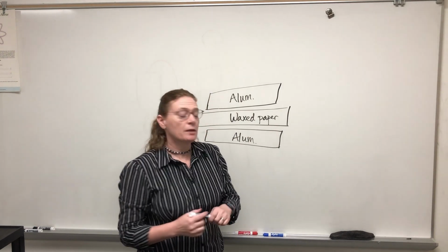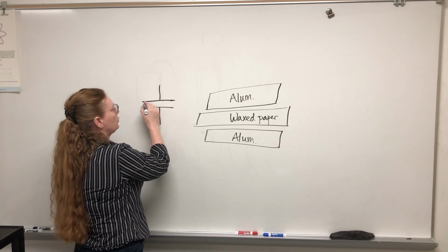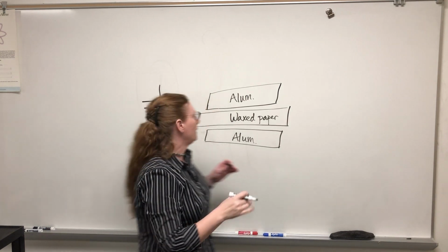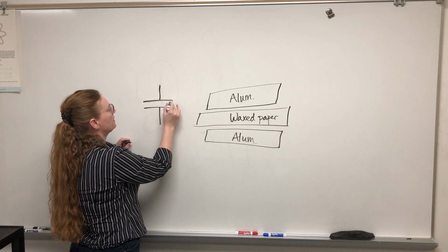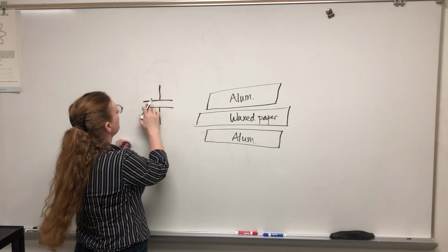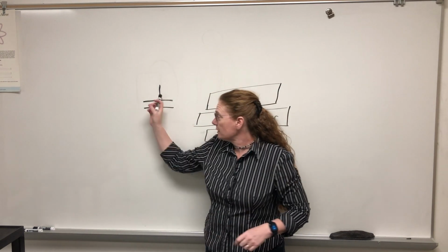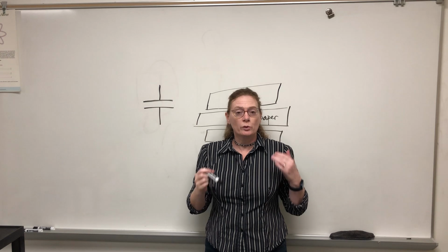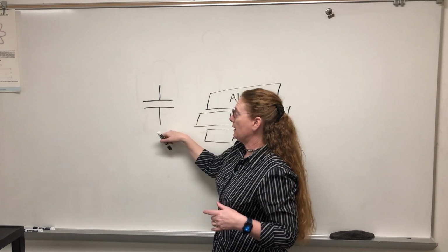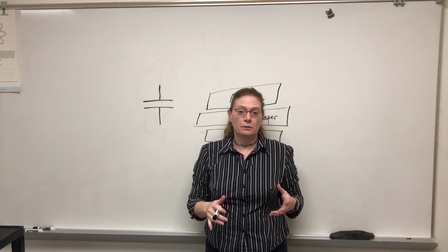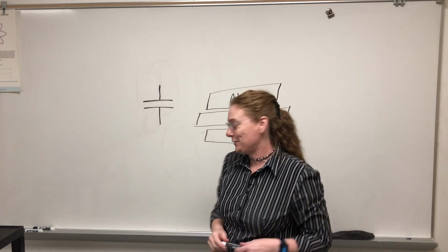The schematic circuit symbol for a capacitor is two parallel lines, kind of like a battery, but of equal width. What these represent: here's my first plate, like the aluminum foil, here is my insulator, and here's my other plate. With a parallel plate capacitor like this, there is no direct path of conductors that goes in one side and out the other. So there is no path of conductors within the capacitor. Keep that in mind for these next couple of questions.